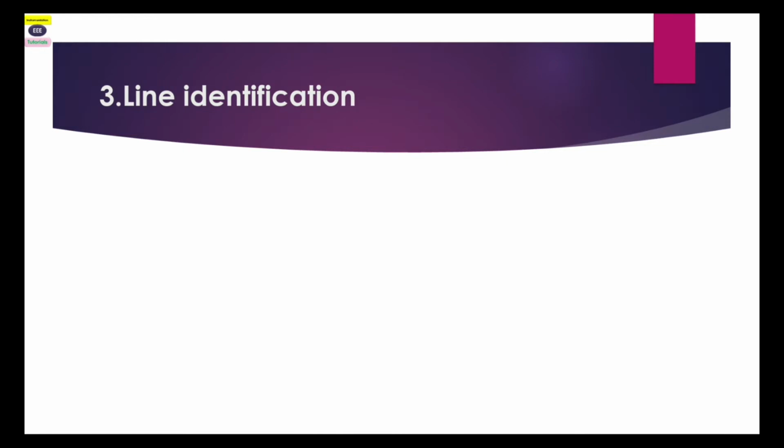Now this is our first very important part which generally you find whenever you are referring any P&ID. So line identification. Generally, if you have one vessel and there are some lines connected in a P&ID, then what is the meaning, how to define this line is simply by the line identifications.